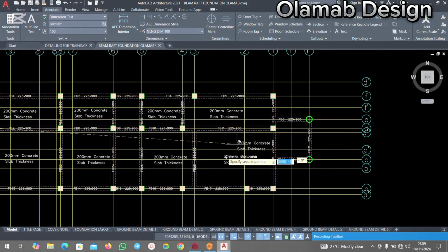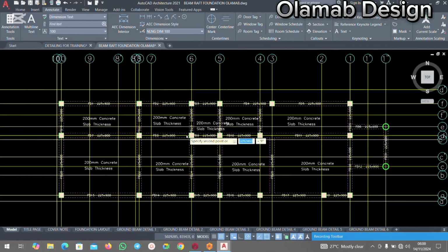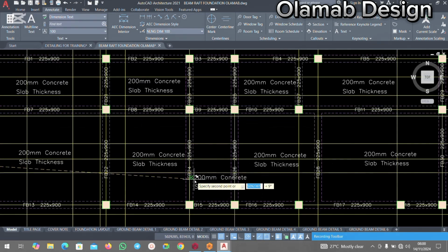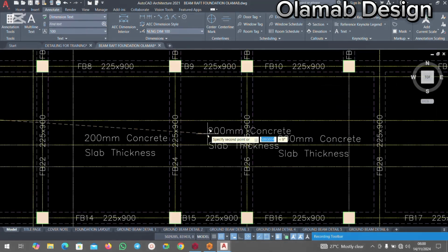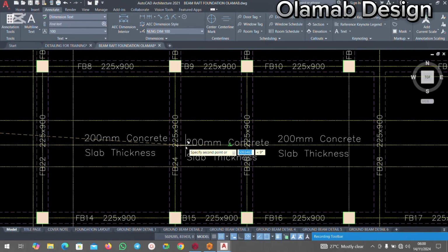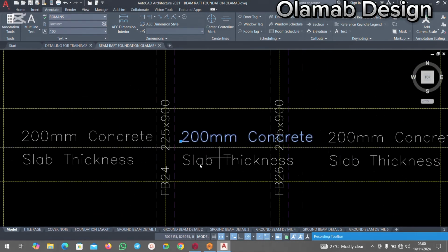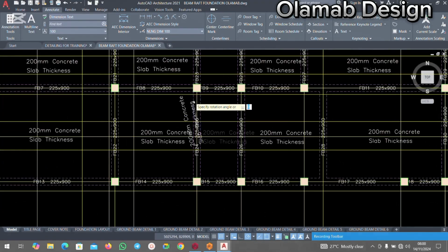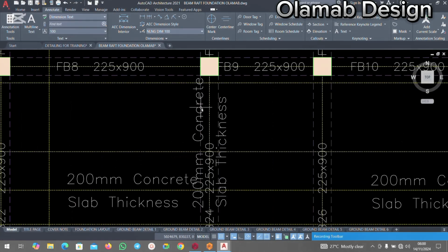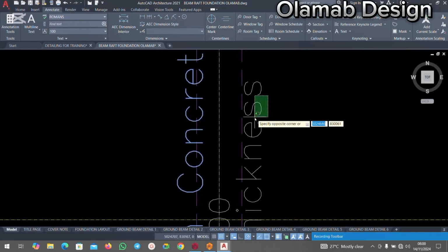Okay. If you are working with your first floor slab, all you just need to do is to make that point a void. Okay, is to make it a void. So for this particular panel now, looking at it, you see that my text is extending beyond the panel. So what I can do is select this. You type rotate on your keyboard, you click on it, then you rotate it this way, then you select it and move it.